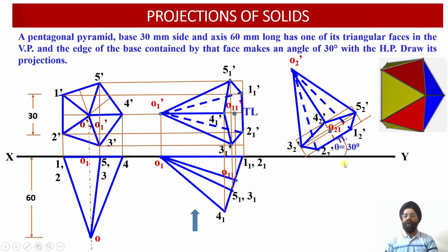Now we want to obtain the 7 points corresponding to the front view projections into the top view projection over here, once the observer looks at this pentagonal pyramid from this side. So projections from all these 7 points we have to draw in the vertical direction, and these projections have to be moved into the top view projection over here.